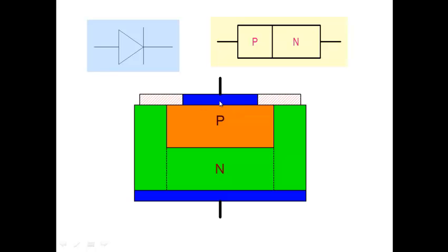All right. We saw in an earlier lecture how such a contact may be made. So this is an ohmic contact. It doesn't do anything to the PN junction except that it allows us to apply voltages and extract current. And similarly, this is an ohmic contact. So in the PN junction, the place where the real action takes place is between these lines here. And this is what is represented in this particular form here, turned 90 degrees.